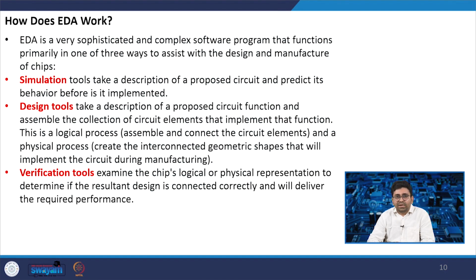How do these EDA tools work? It is very sophisticated and complex software that functions primarily in three ways to assist with the design and manufacturing of chips: simulation tools, design tools, and verification tools. Simulation tools take a description of the proposed circuit and predict its behavior before it is implemented. Design tools take a description of the proposed circuit function and assemble the collection of circuit elements that implement that function. This is a logical process. Assemble and connect the circuit elements, and a physical process creates the interconnected geometry shapes that will implement the circuit during manufacturing.